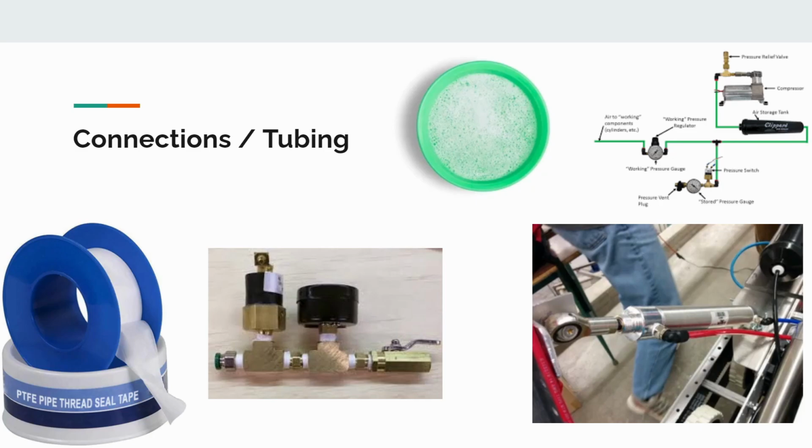To operate that, you just pull out the top of it, turn it to whichever PSI you want, and then push it down to lock it in place. And then the other side of that pressure gauge goes to your solenoids and then to your components, your actuator, pistons, and such.